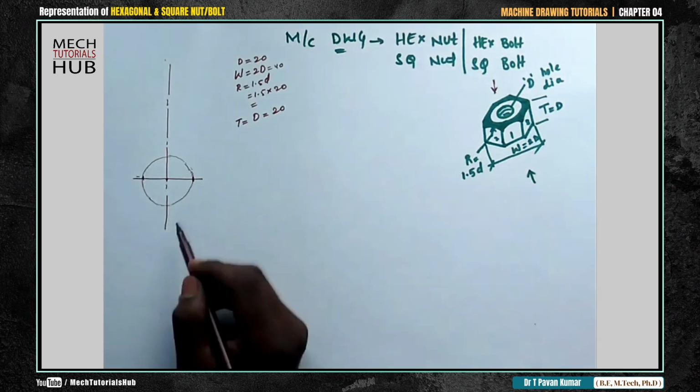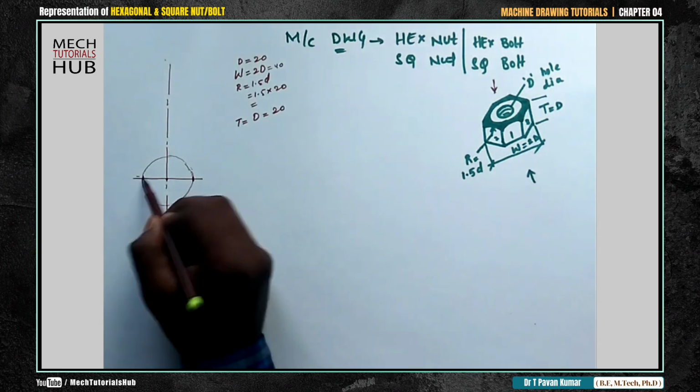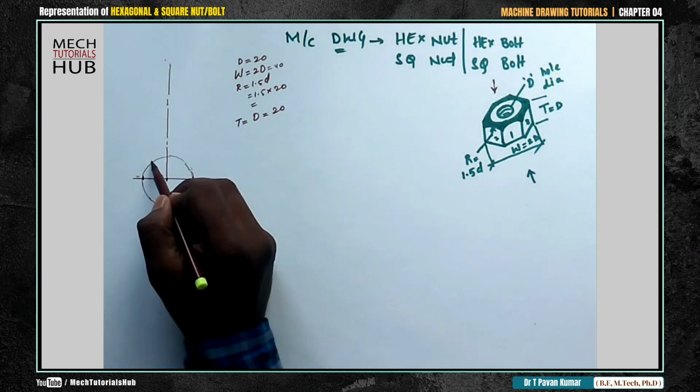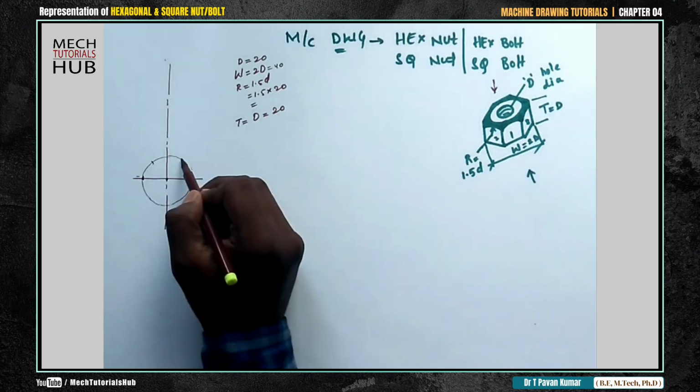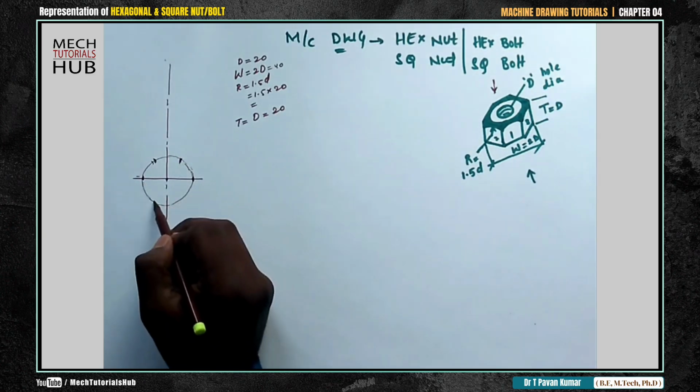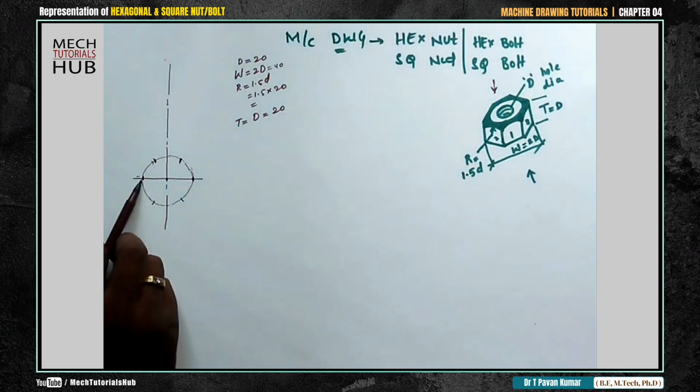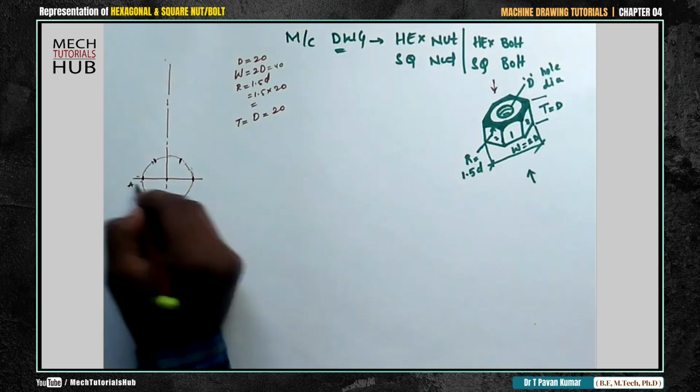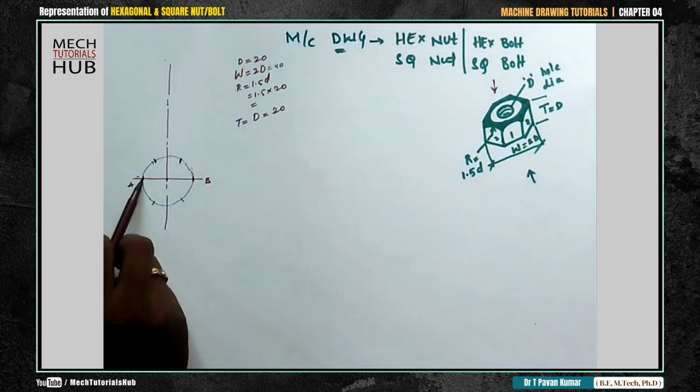Now considering D as the radius, make markings from here. Taking this as center, make a mark of D. This as center, make a mark of D. Again from here, D on either side. Take this as center. Let us name it as A, B. Take A as center.